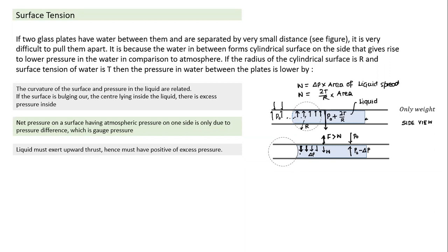And if it has to be lower, just see that one now. So this is a region with the curves, this surface here, it will take a curved shape of radius like this. Their pressure is atmospheric. As I cross here, I am going from inside the liquid to inside the curved surface to outside the curved surface. So pressure will drop by delta P here.